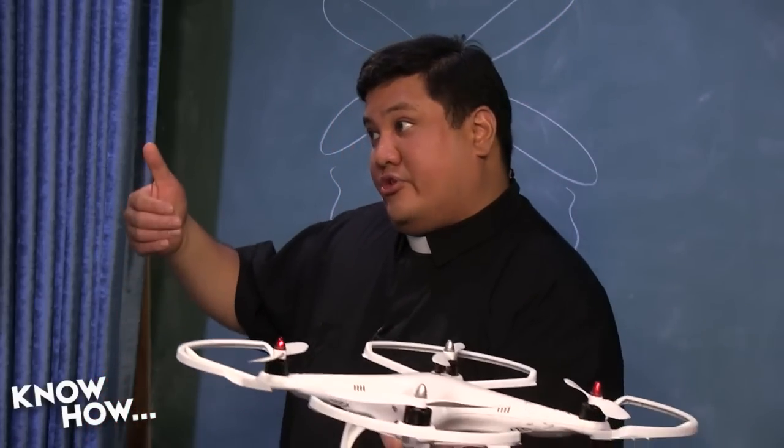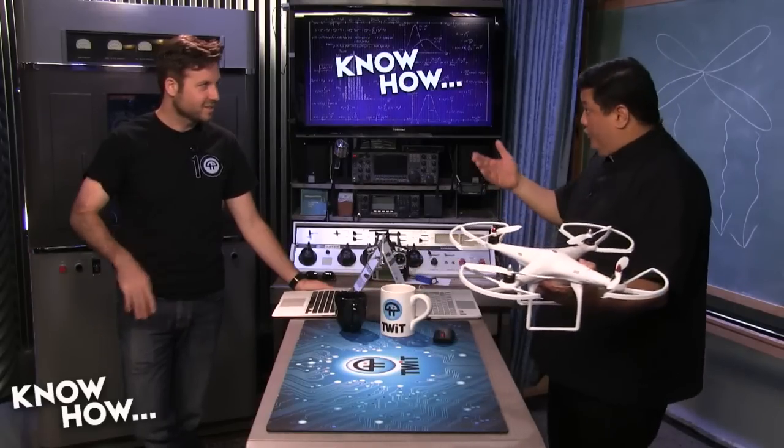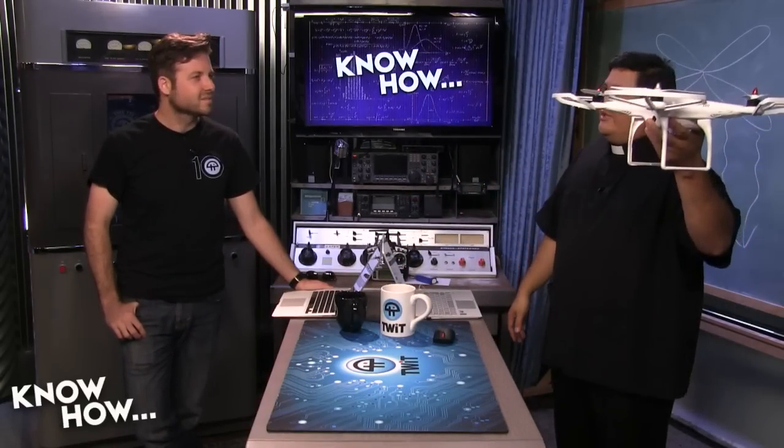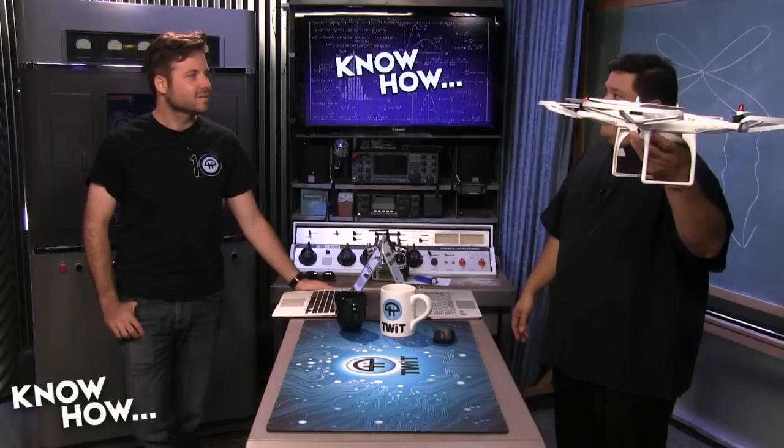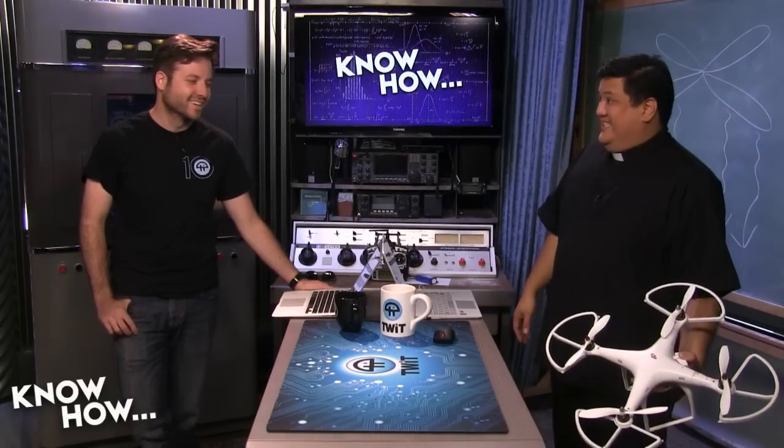If you've been flying around a quadcopter, as you come down, right before you hit the ground, you kind of goose the throttle so that you flare out and kind of land easily. Give yourself a little cushion. Exactly, so that will work. But if you're in that vortex ring state and you goose the throttle, you'll actually drop faster, which is kind of scary. Yeah, definitely, especially if you're actually inside of the craft. If it's a full-size helicopter, you're not just going, oh man, I broke the arm. It's, I broke my arm or killed myself.